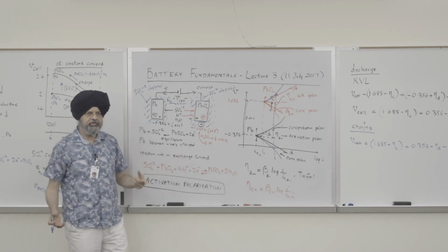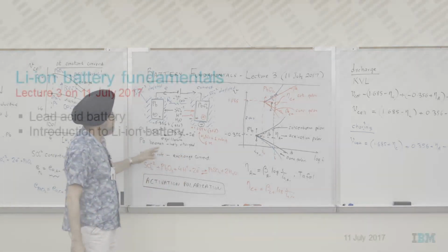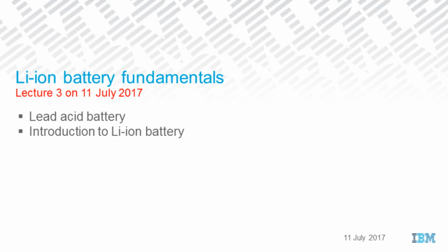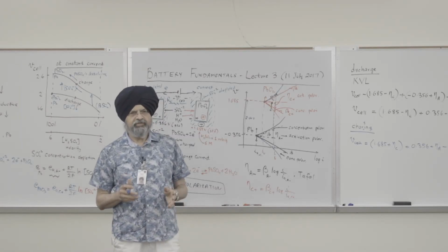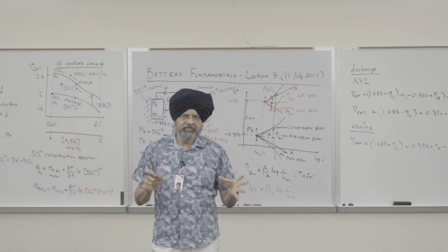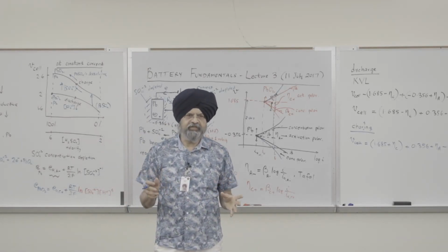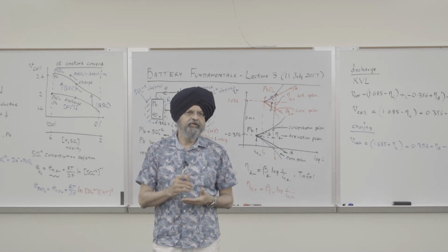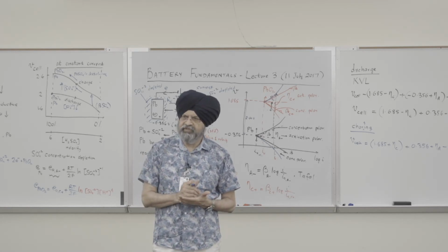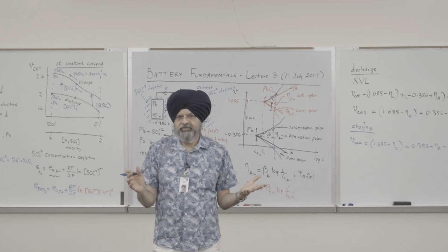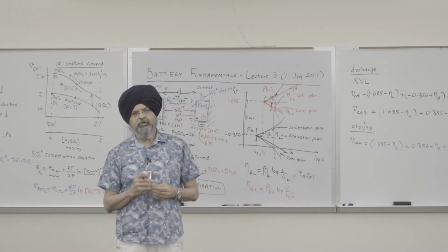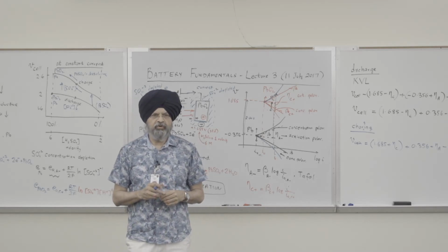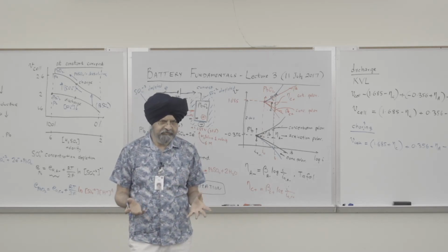But to your question, so this 2.04, that's the cell voltage under standard conditions. Except I think when I say standard condition, I should say 1 molality for the sulfuric acid, but it's 6. So the voltage will change depending on the concentration of the sulfuric acid.